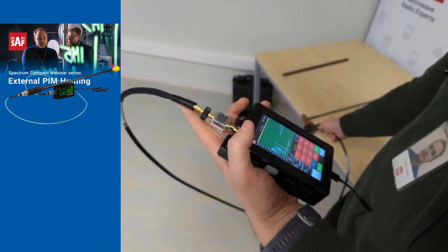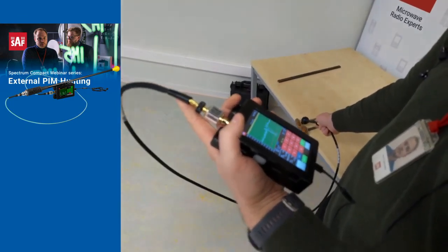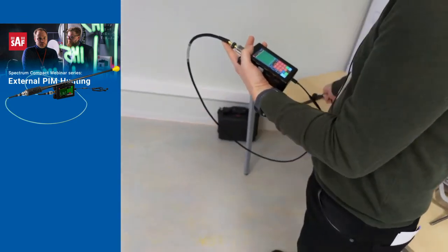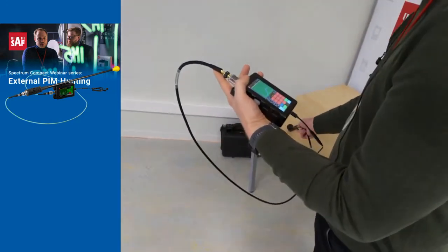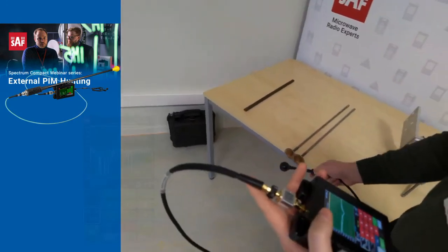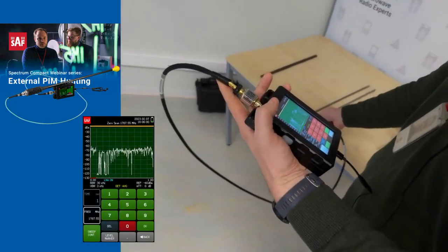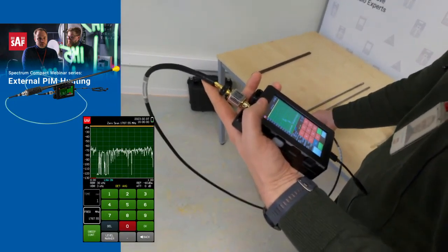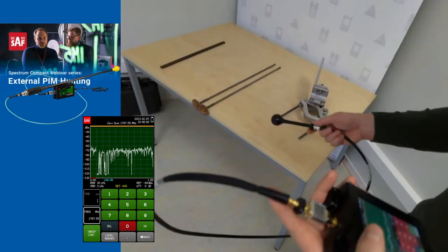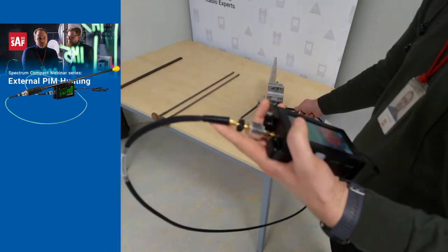Once we touch the device with the probe, it is vibrating, so it gives additional peaks from that. If we go further, for example, we test it here, we do have some PIM readings on this material as well. Since we touch this one, it is very apparent that here the intermodulation products from those two carrier frequencies are generating very intense PIM.